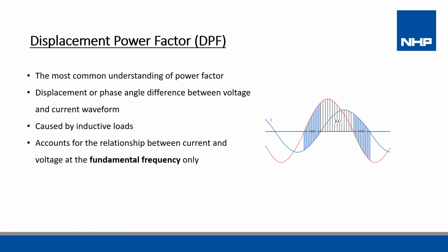Note, for a site where harmonics are present, displacement power factor may represent a small percentage of the overall true power factor. If there are no harmonics present, then displacement power factor would be equal to the total power factor. Also note that commonly used equipment to compensate for power factor only improves lagging power factor.